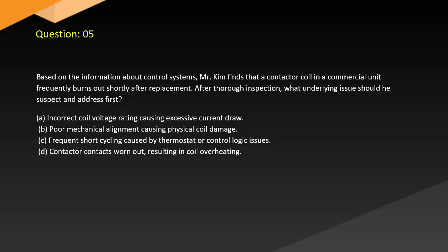A. Incorrect coil voltage rating causing excessive current draw. B. Poor mechanical alignment causing physical coil damage. C. Frequent short cycling caused by thermostat or control logic issues. D. Contactor contacts worn out, resulting in coil overheating.